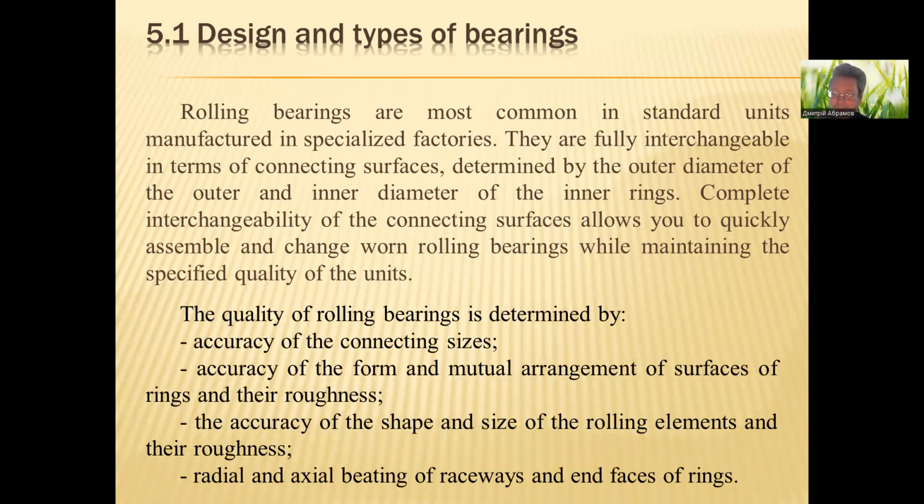The quality of rolling bearings is determined by the accuracy of the connecting sizes, the accuracy of the form and mutual arrangement of surfaces of rings and their roughness, the accuracy of the shape and size of the rolling elements and their roughness, and radial and axial runout of the raceways and end faces of rings.